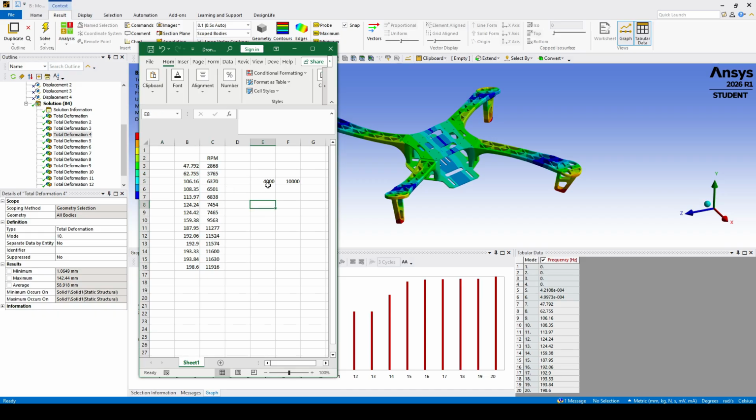It would be better if we run the quadcopter exactly in between, so we have some space. I see here 4,500 RPM. It will be a good start, so we prevent any resonance, because you always have to take some safety factor.